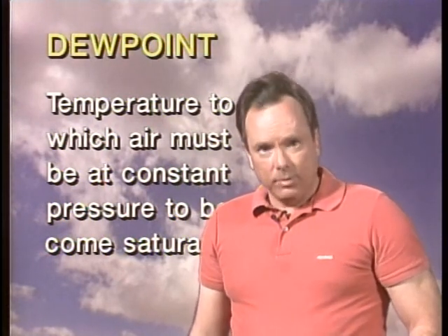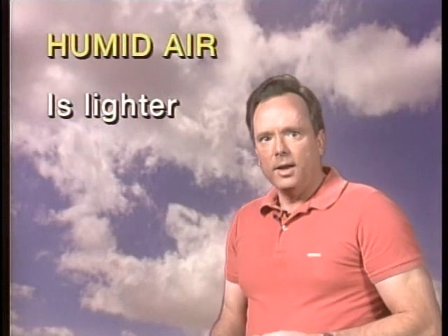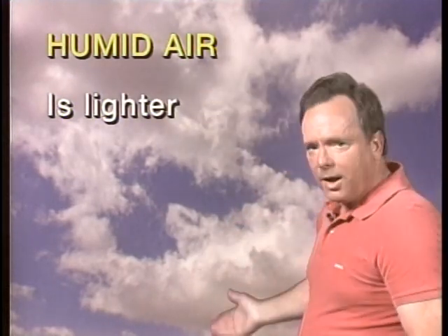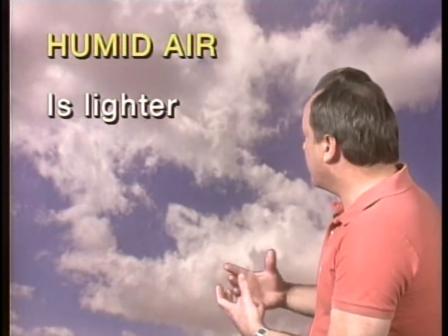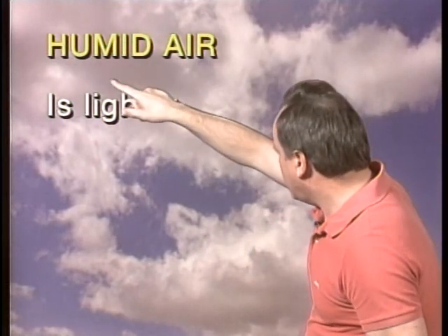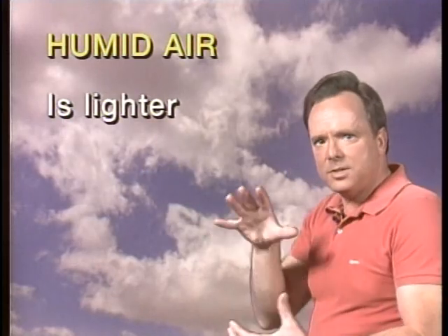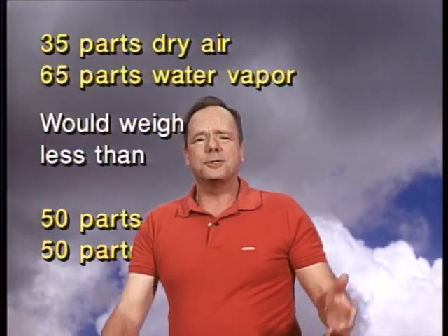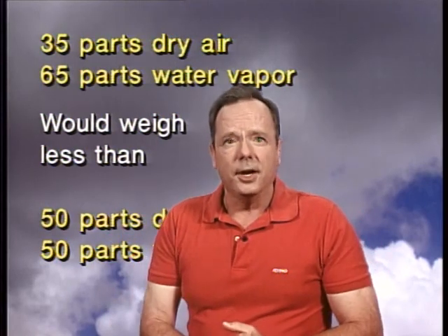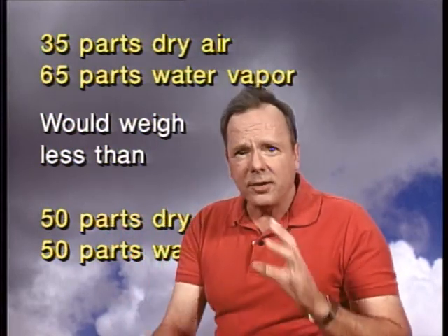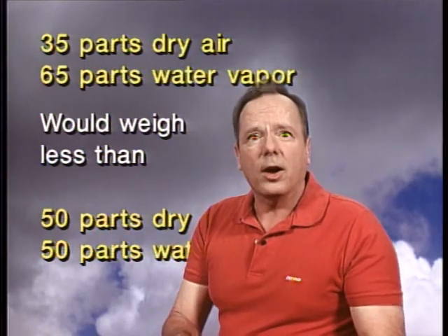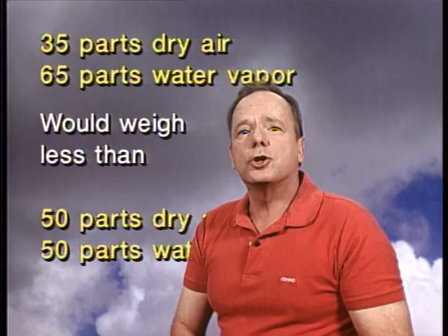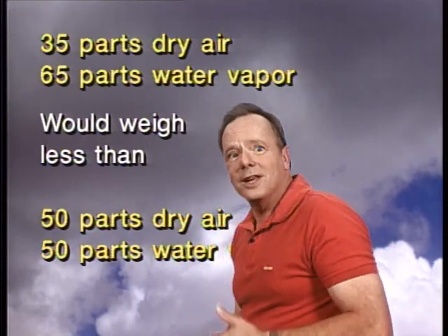Now let's talk about the density of humid air. Is humid air more or less dense than dry air? And the answer is water vapor in the air is less dense, and humid air is actually lighter, less dense. So they're going to ask you a question about this on the test, and the answer is very, very easy. All you have to do is remember, anytime you have a mixture of air and water vapor, the more water vapor the mixture has, the less the mixture will weigh, because water vapor weighs less than dry air.